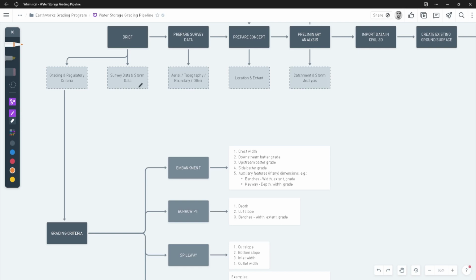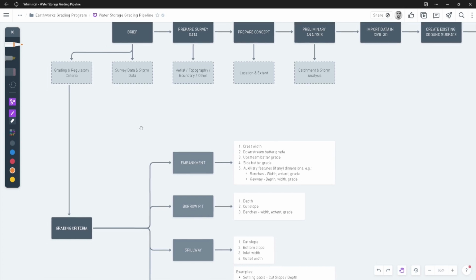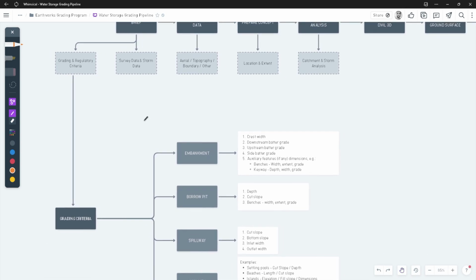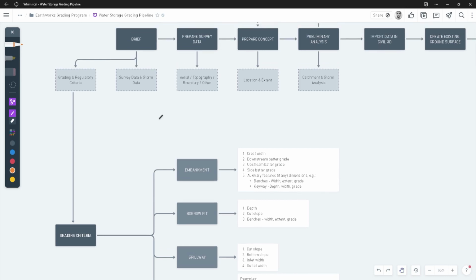And I would nowadays even say go as far back as you can, possibly 500 years if you can find data like that, because honestly, I don't want to get into the whole climate change thing, but we have been building structures according to the 100-year data, and they just weren't sufficiently sized, and they had issues and had to be resized during a storm because they just weren't large enough to accommodate those 100-year events, because they're just bigger than the 100-year events that were recorded in the past.